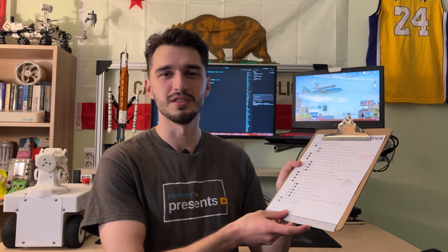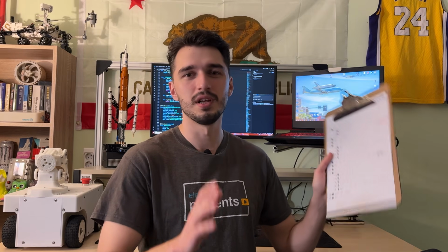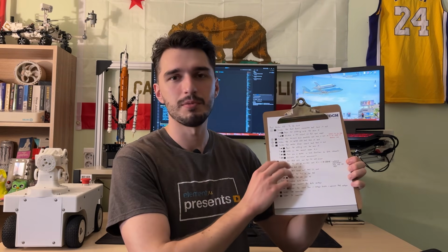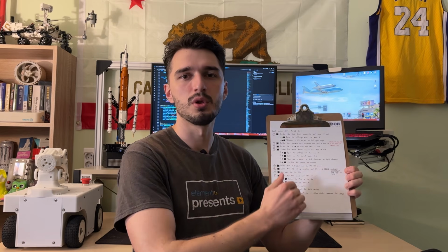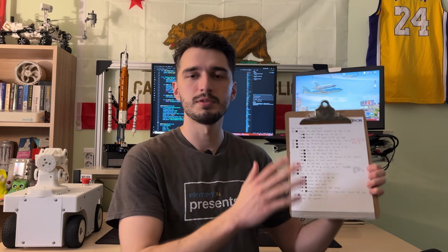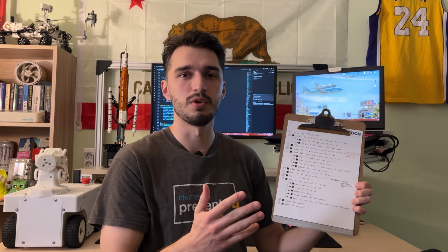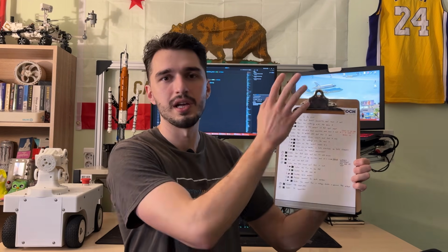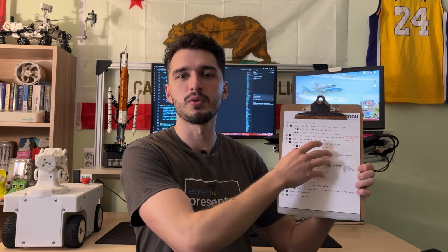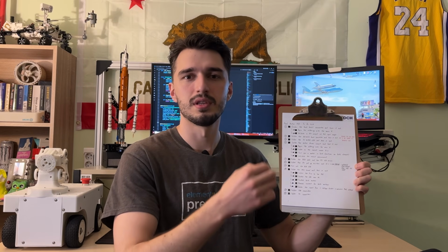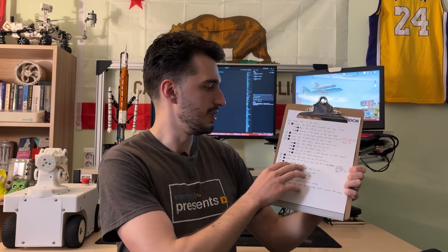Before we start soldering the PCB, I want to share another tip with you, and that's another checklist. It's a bunch of checklists, but trust me, they'll save you a lot of time in the long run. So what I do is go through my EDA software and make a step-by-step guide literally for me on what I need to solder, in what order, and how to test it. And this is especially important for new designs where you're not sure what's going to work and if anything is going to work. So for example, for this board, I started with the buck boost converter, then I went to the buck converter, then the LDO, followed by the motor driver, and I would test each segment step by step, as you will see in the upcoming clips.